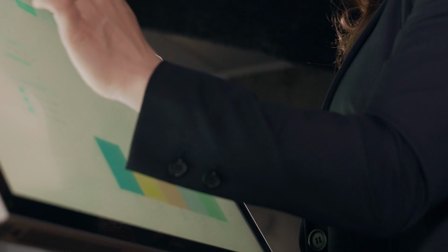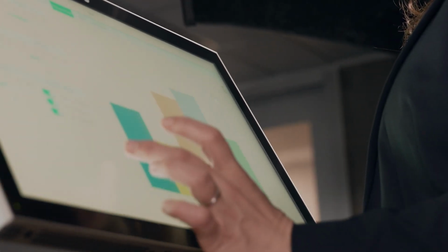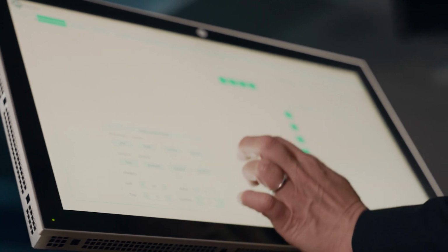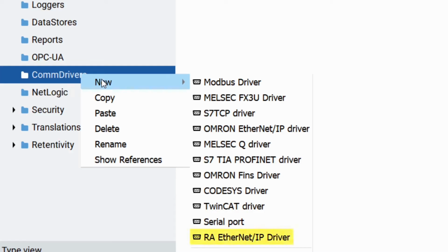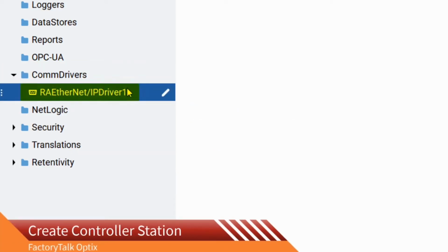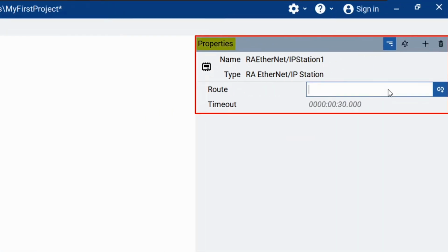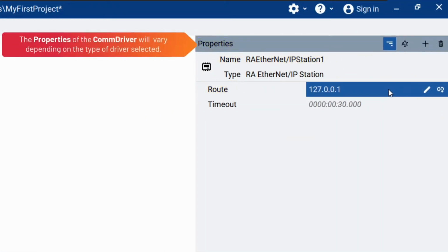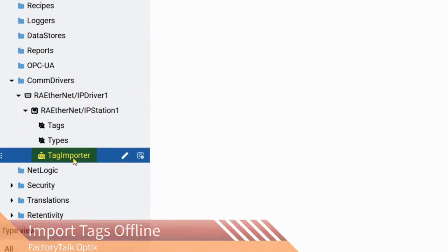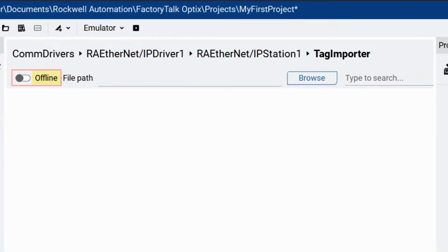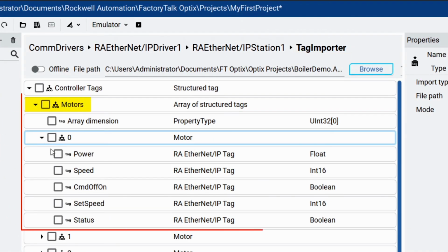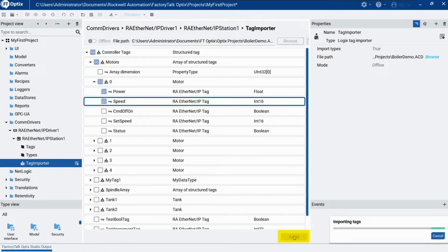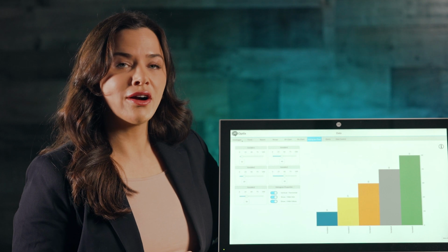So, OEMs and integrators don't need to travel to end-user sites to apply solutions to issues. Via Rockwell cloud infrastructure, remote engineers can see and interact with a mirror image of what's on screen for remote troubleshooting and maintenance. When OptixPanel Standard terminals are employed as communication gateways, they even allow changes to connected controllers. Here, an engineer connects from their facility through a VPN, through the FactoryTalk Hub, through the OptixPanel terminal, to the controller. This FactoryTalk Hub is the Rockwell Automation cloud infrastructure that provides remote connectivity to FactoryTalk Remote Access and the infrastructure for FactoryTalk Optix.